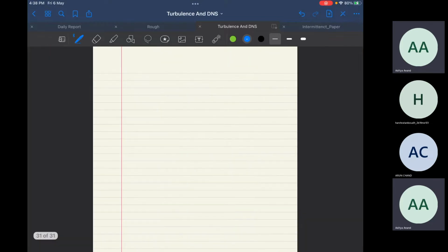So we have now large eddy simulations. In DNS we were solving for the instantaneous velocity field u(x,t). In LES, we'll solve for the filtered velocity field, the velocity field filtered at scale r. Let's call it u_F.